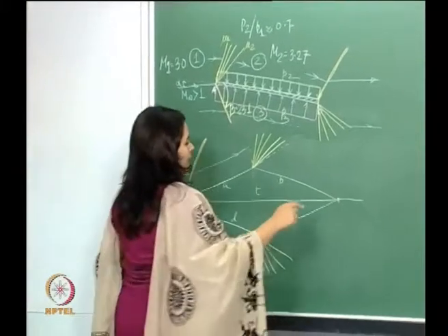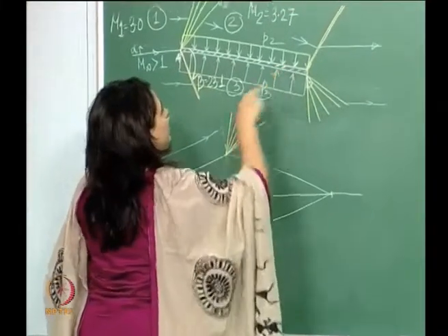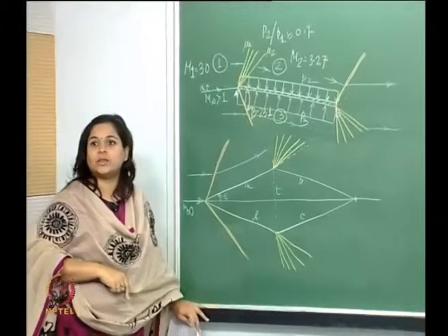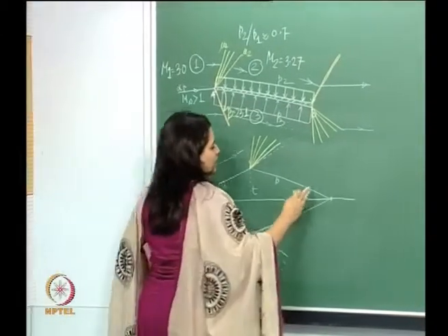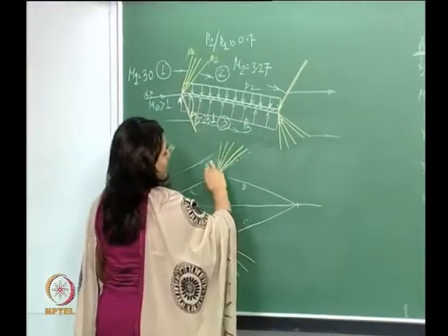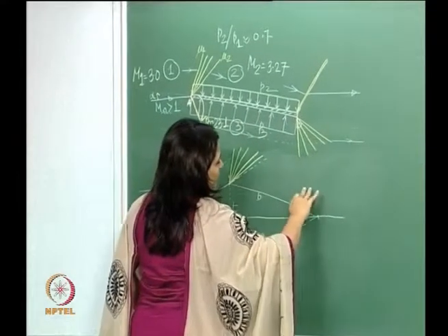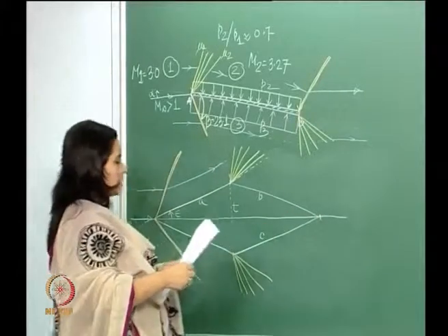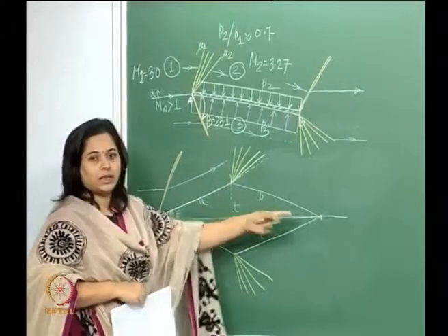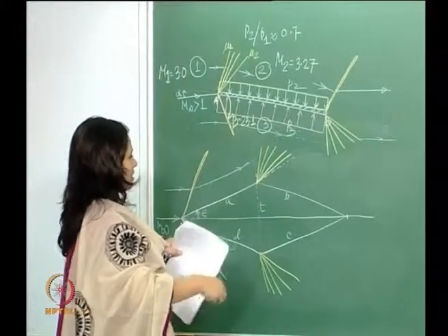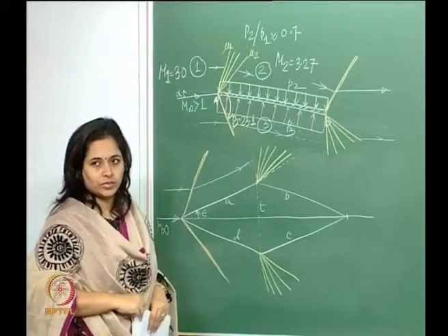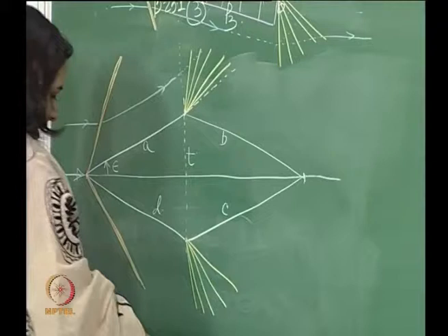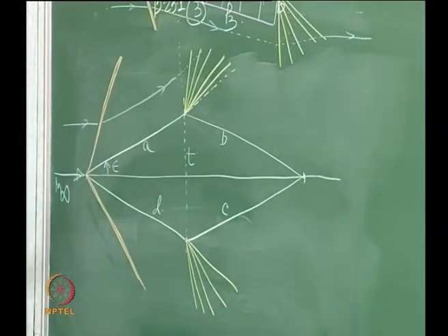And again at the trailing edge, we will use the same explanation that we did there, because now it has to join the free stream. Here it has expanded. So, it is moving this way, and you want it back in the free stream. So, you shock it. So, we will basically have again two shocks here, so that it goes into the free stream. So, now our job again is, if we have something like a wedge shaped body like this, how do we calculate the CL and CD?